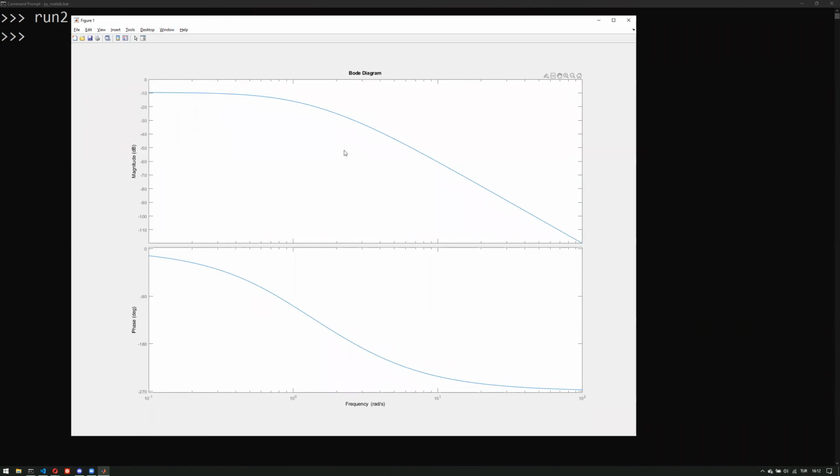The root locus did give us an idea about the unit feedback with a static controller or static coefficient. So we were trying to choose a certain k value. But most of the time, the root locus is used for step response manipulation. Therefore, it's more of a transient design tool. Here, the Bode plot is a steady state plot.